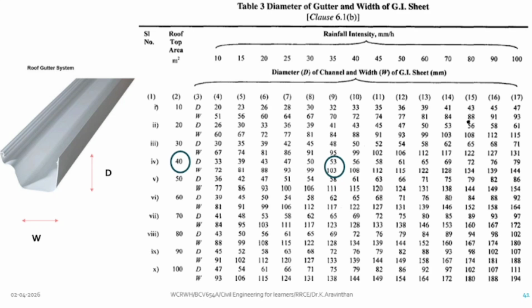So what is the length? This is 3 meter, 3 meter, 3 meter. So totally 9 meter. Now what is this breadth? 8 meter is this one. We have already measured. That is why I am saying. So 9 into 8 is how much? 72. So for your class, you have to take rooftop area as 72. Do you have 70 here? Do you understand how to design? You have to measure the area and take the 70 or 80 you have. Whichever is higher you take it. 72 is there, hence you take 80.